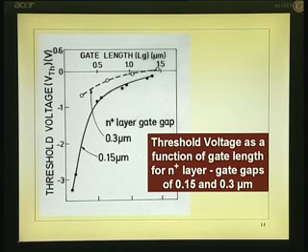So, this is the threshold voltage effect. On the x axis, you have got the gate length, not channel length, gate length 0.5, 1, 1.5, 0.25. Okay. You can go down right up to 0.25 micron channel length. Then if you measure the threshold voltage by that root ID versus VGS minus V threshold, you can plot, you can get the threshold voltage.